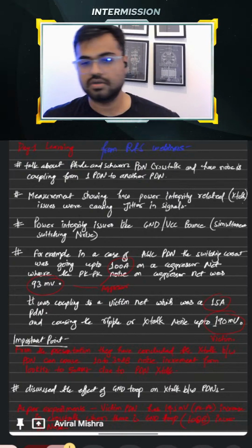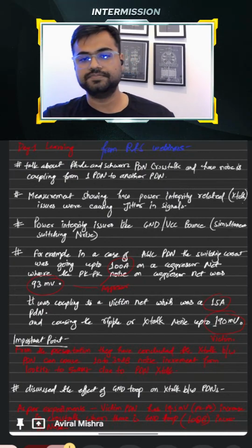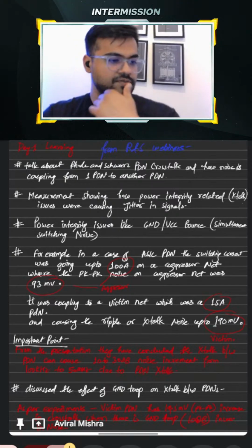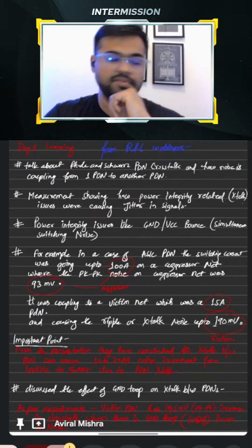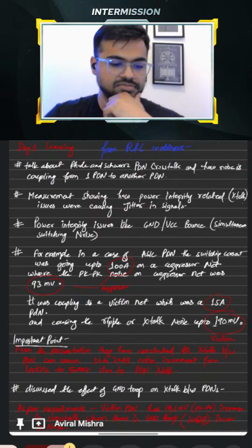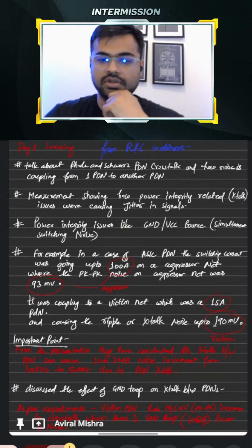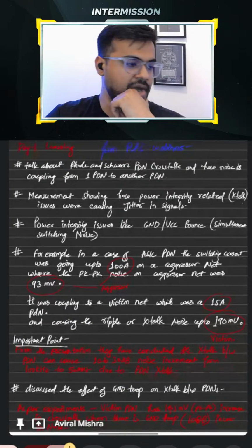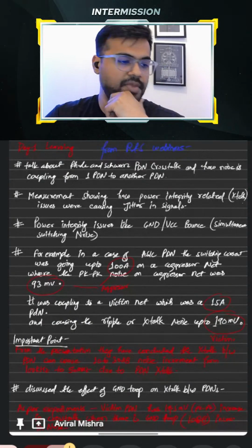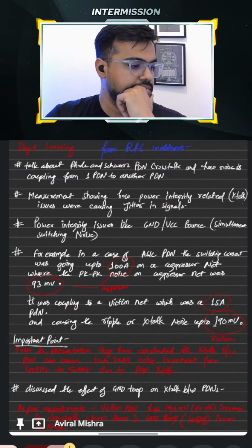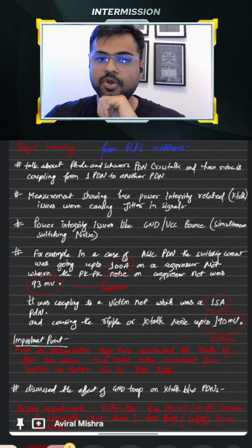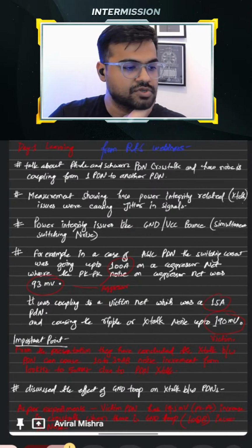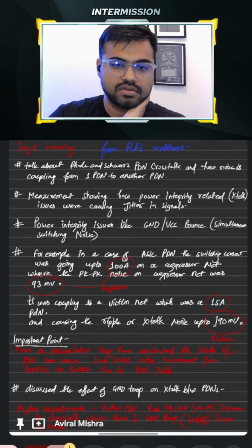Yes. So that is what we call PDN crosstalk. Now, from that workshop, we know this can happen due to a ground loop or due to ringing on ground or power planes. The important thing was that this PDN crosstalk was causing jitter on digital signals.